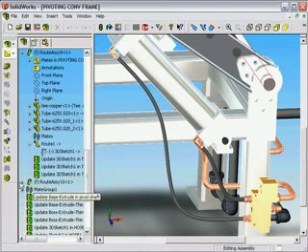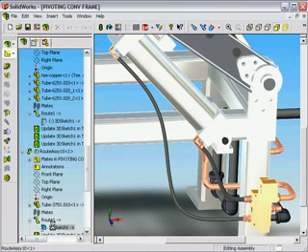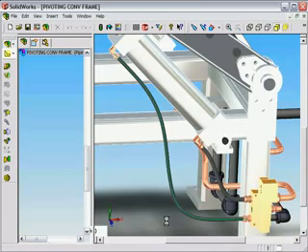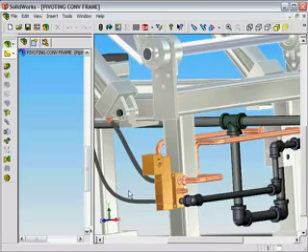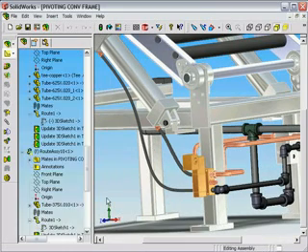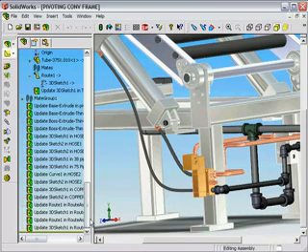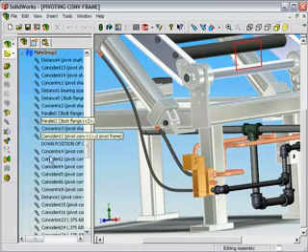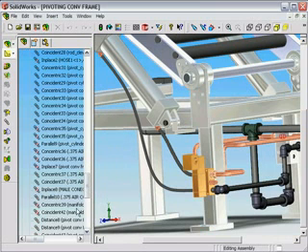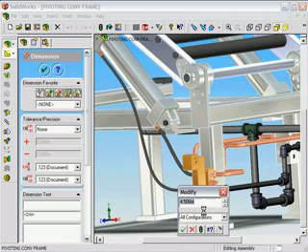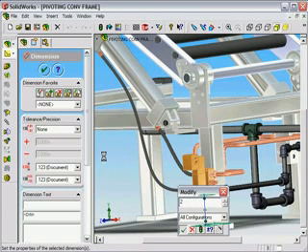Now, one thing that's always constant in design, and that's change. SolidWorks Routing captures design intent. And the most powerful portion of this is the ability to handle change. When your assembly changes, all your tubes need to update. We're going to change the distance made, changing the position of the manifold in the assembly. Maybe we need to move it down for clearance purposes.